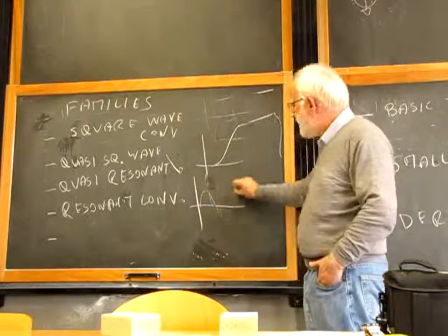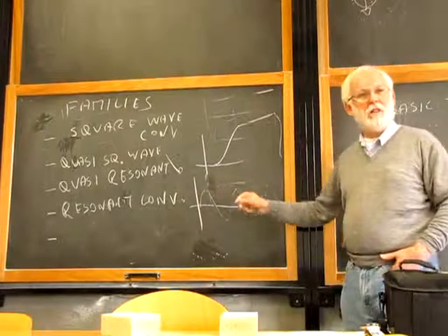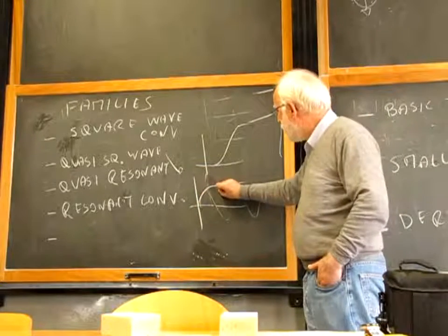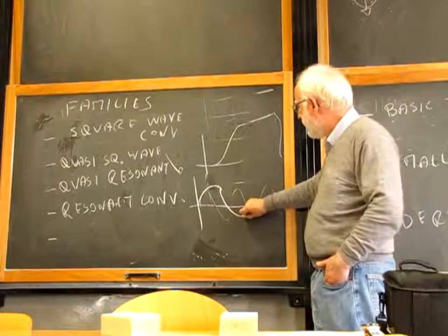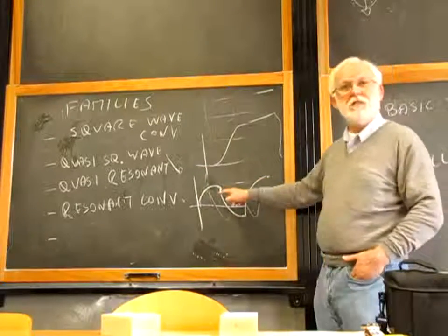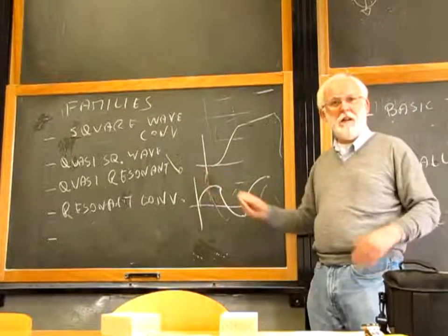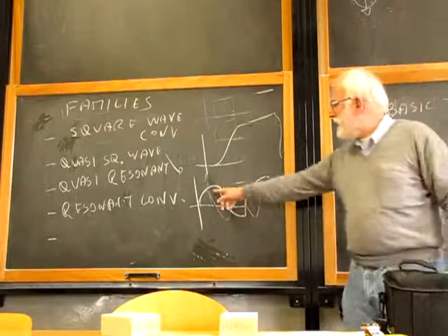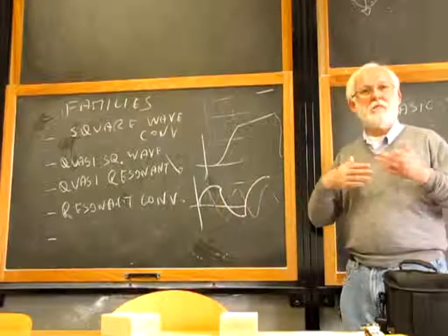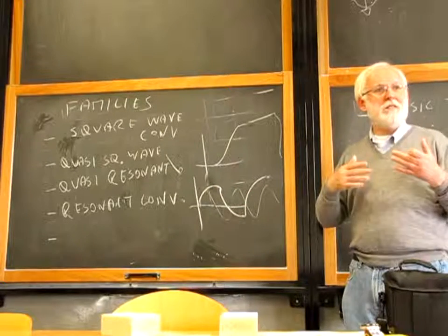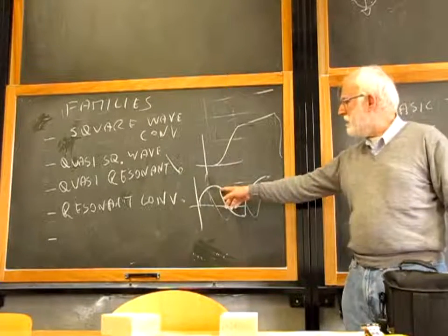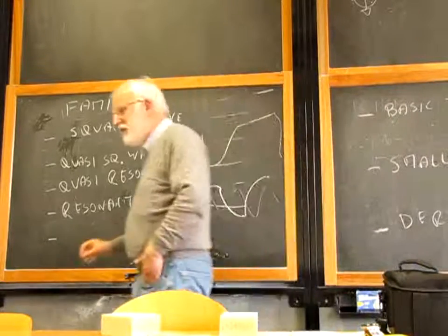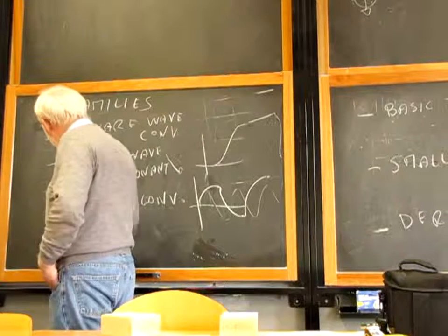It's not a sinusoidal periodic forever. You can have a part of sinusoidal to this point, then you start another sinusoidal like this, then you start another sinusoidal like this. Those are not exponential. Those are arcs of a sinusoidal waveform, because you have an LC resonating, and when the switch opens or closes, the circuit changes and your behavior can change. And the other one, not used so much anymore, is the multi-resonant